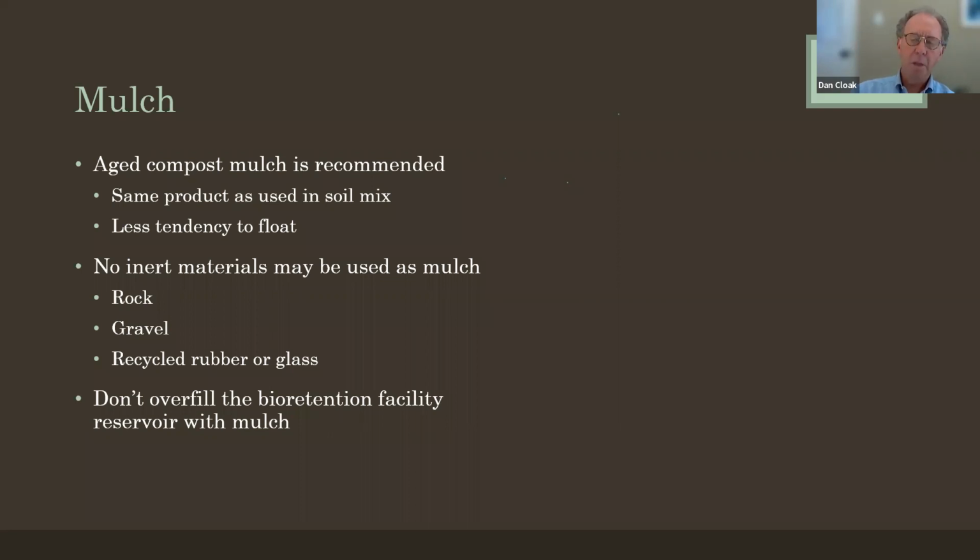That doesn't mean that, particularly in an adequately sized or even oversized bioretention facility, particularly if it's one that's being designed for active or passive recreational use, you can't have some variety of coverage in there. But overall, a bioretention facility with rock mulch on it, there's a few problems that are going to result from that.